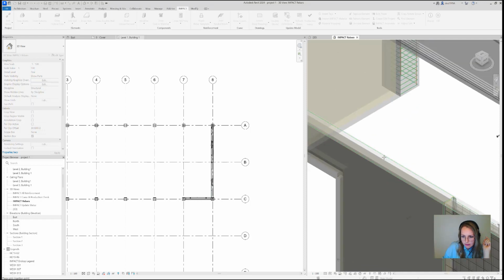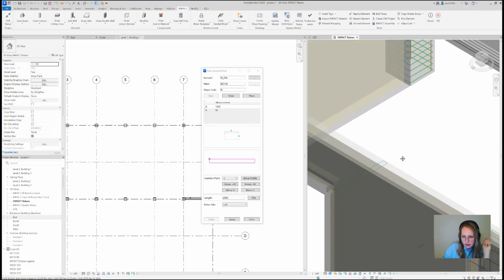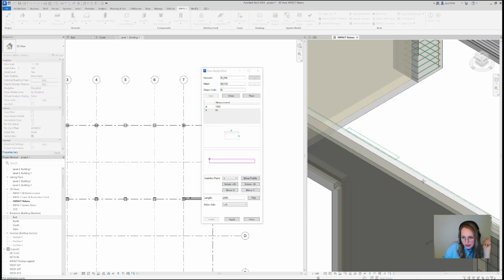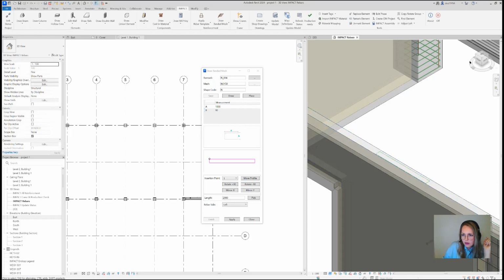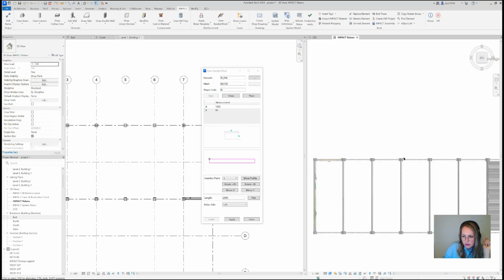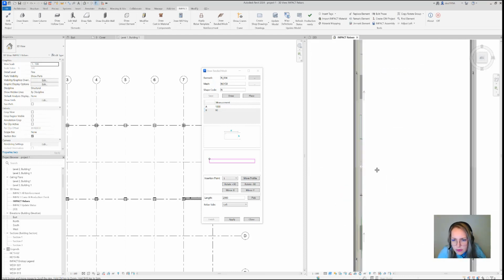Okay. And here are some insertion tools. I think I need to rotate it, and I need to move it. First you select the insertion point, and then you move according to it. So I need to go on a top view to find out if I'm doing correct what I'm doing.